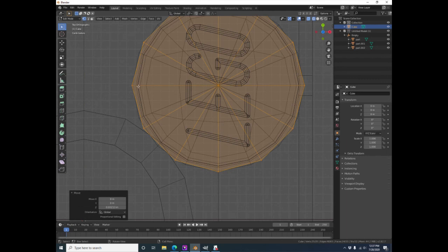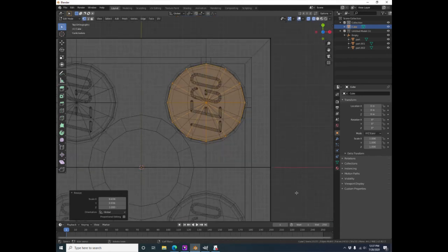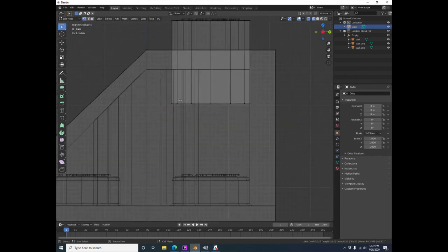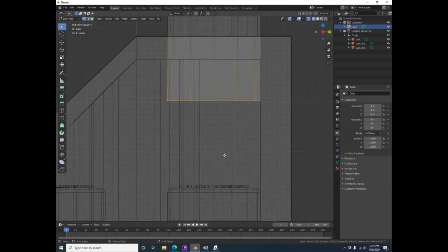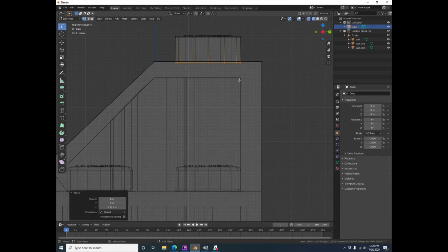So we've got to align to actually these edges in here. So again, that's just S, and then if you hit Shift Z, that's to scale in the Z plane. So that will scale for us without changing our Z position, as you can see here. And then let's bring up the bottom of this stud close to the top of the brick that we built. So again, we can use a box select to select everything from this view. And we're going to go G Z again to translate it up. We want it to overlap a little bit.